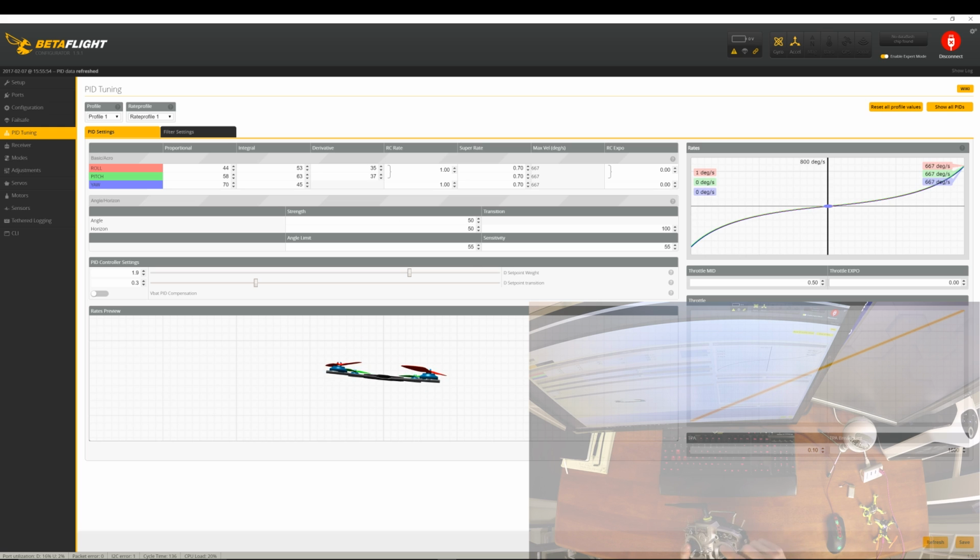If you want to decrease the value, again you leave it on D and then bring it down. You'll notice the blue light flickers a little bit, and then we'll stop, and notice that this 3537 decreased to 2426. So as we're flying, we can tune P, then move on to I, and then D. While it's in the air, we can be increasing or decreasing those values with this potentiometer inside. This is a pretty slick way. It really makes tuning a lot easier and a lot faster.